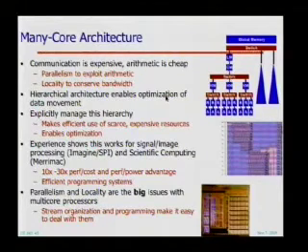And I can schedule transfers from off-chip to on-chip using just-in-time inventory management techniques to make the most efficient use of this scarce on-chip memory by holding data only during the minimum period of time it's needed. And most importantly, I can factor the surprise out of the inner loops of the program. All the surprise in terms of unpredictable memory latencies is dealt with by doing these bulk memory transfers.